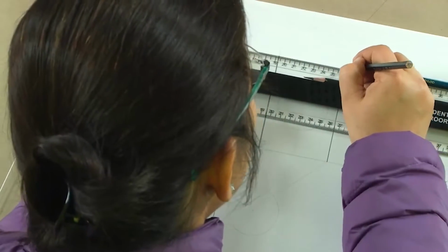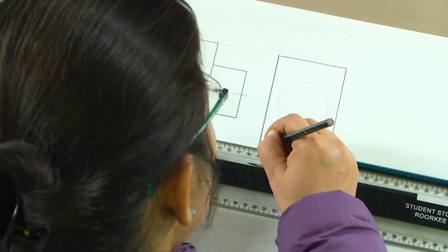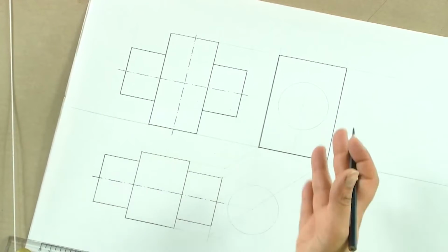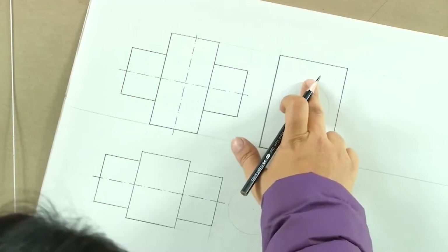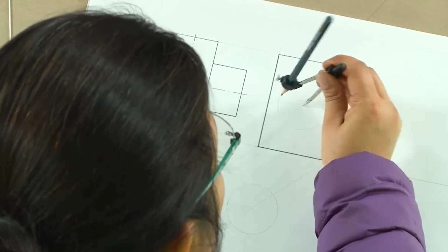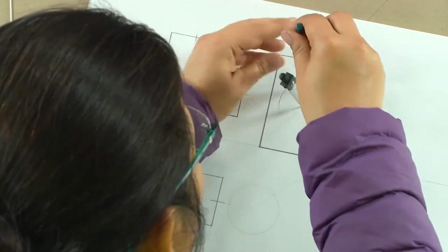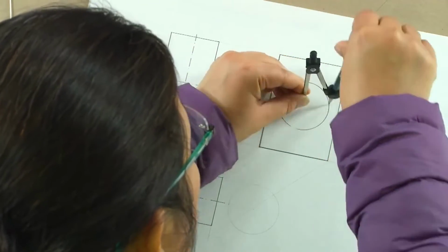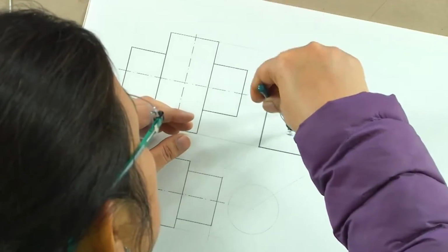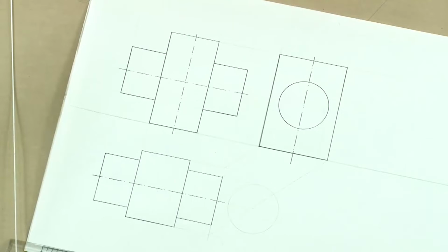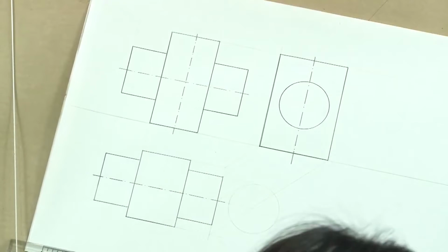Now, this is the simplest case because the circular cylinder is actually being cut by a plane which is the surface of this prism. So, this circular cylinder is cut, and hence we will actually be seeing the circle here. There is no change in the original shape of this cylinder, the base remains the same. So, it is a simple case. The only thing we have to remember is where the axes are intersecting and how they are intersecting. So, this was a simple case which we started with. This is the axis of the prism, and that is what we get when these two intersect. That is how the orthographic projection drawings would be.